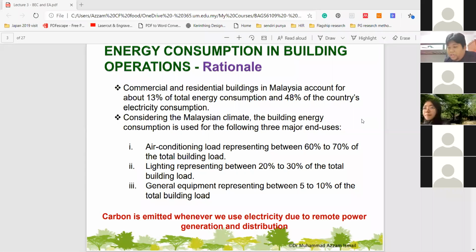It'll still be cold, your room will still be cold enough. The air conditioning will be maintaining a certain relative humidity within your room, but it doesn't have to really freeze up the room in comparison to the other setting. So it's just a matter of pressing a button to change the setting. So running at 25, running at 26, if it's too cold, running at 26 or 27 degrees for that matter, run it at the water drop setting, right?